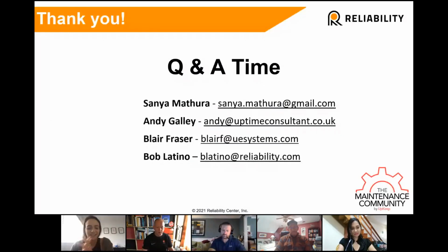Have a really good CMMS system. You can utilize that. The output of the RCA goes into a work order to be actioned, I think. And then obviously you tag the RCA to the work order so you can be tracking that over time. It's something I used to do in predictive.